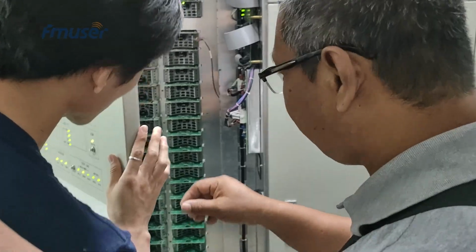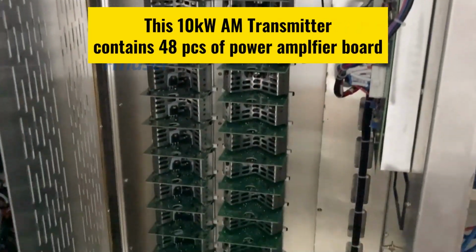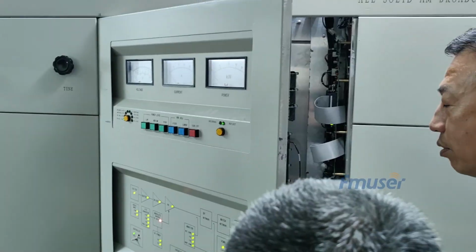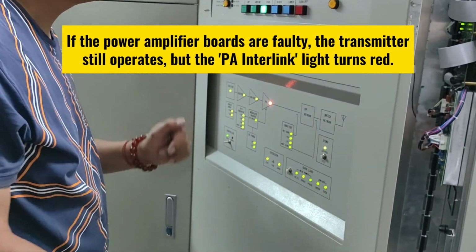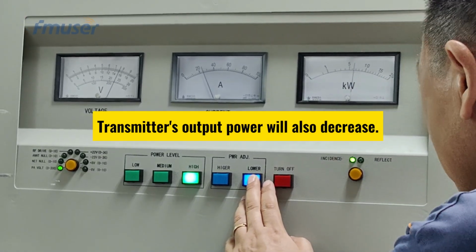the power amplifier. In this particular case, the transmitter consists of 48 power amplifier boards, each forming an integral part that cannot be separated. Consequently, if any of the power amplifier boards are disconnected prior to startup, it will prevent the adjustment of the transmitter's output power. In other scenarios, if a power amplifier board becomes faulty, the transmitter will still operate, but the PA interlock indicator light will change from green to red. However, the transmitter's power output will decrease.